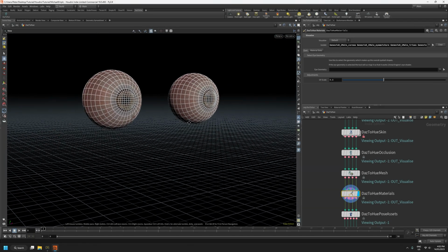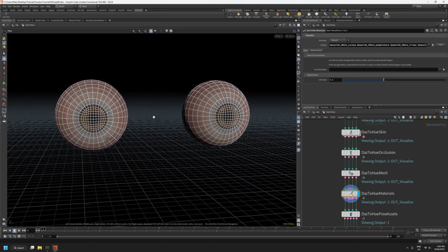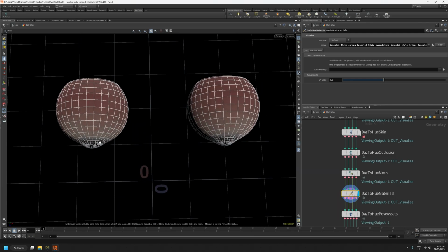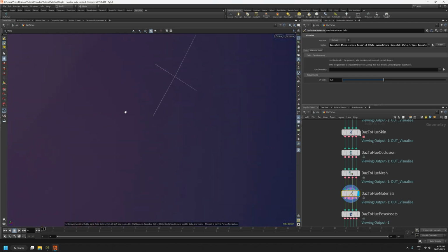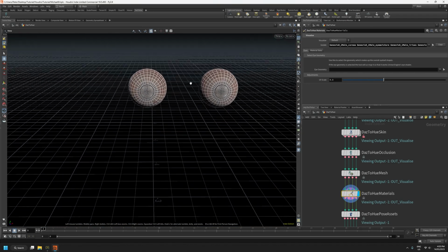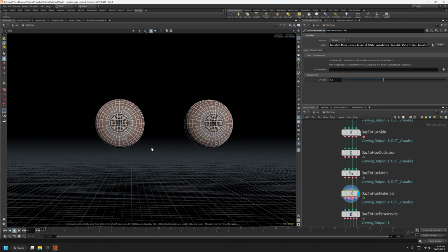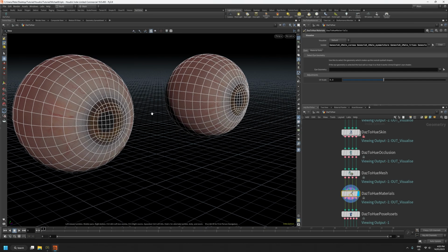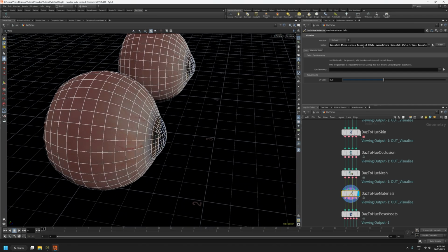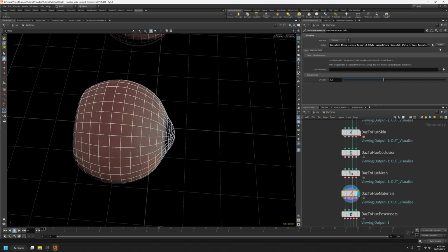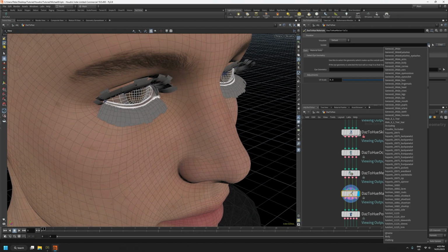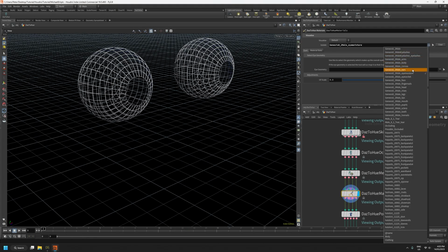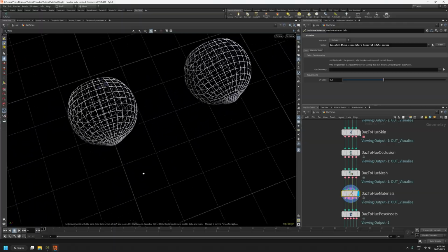Now, in order to get these eyes to look right when the Unreal Engine eye shader is applied, what we want to have is just the overall eye geometry shape. You don't need any of the internal parts of the eye. Once we have that, we just want to apply a front-on UV projection for both eyeballs. Now for Genesis 8 and 8.1 characters, to get this overall eye shape, we just need the eye moisture geometry and the cornea geometry. Both of those combined will give us this overall eye shape. So if I clear isolation and just select those two, our eye moisture and the cornea, you can see now we have that overall eye shape that we want.